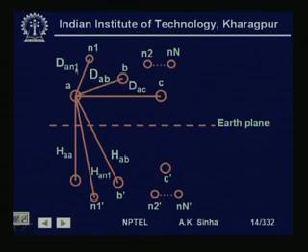As we had seen earlier, we can take care of this by means of using the effect of images, as we had done for calculating inductance and calculating the resistance. So, here again, since these conductors are above the ground, what we are doing is we are considering the image conductors below the overhead conductors, again at a distance which is equal to the distance of the conductor above the ground.